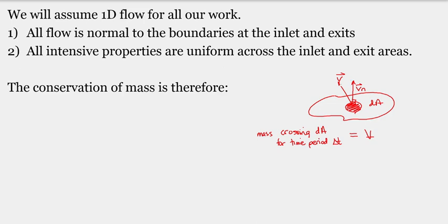Okay. So if this is the velocity of the mass, a velocity vector, the mass exiting that system, we can take this area here, and we know that it's going to be projected in this direction here, and that's the slant cylinder. So this is a slant cylinder, and it's essentially the cylinder of space, or the volume that's swept out by the mass moving through this little differential control volume.